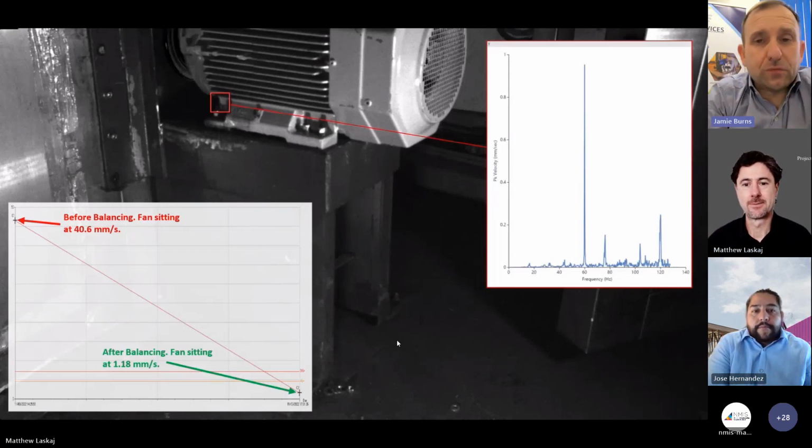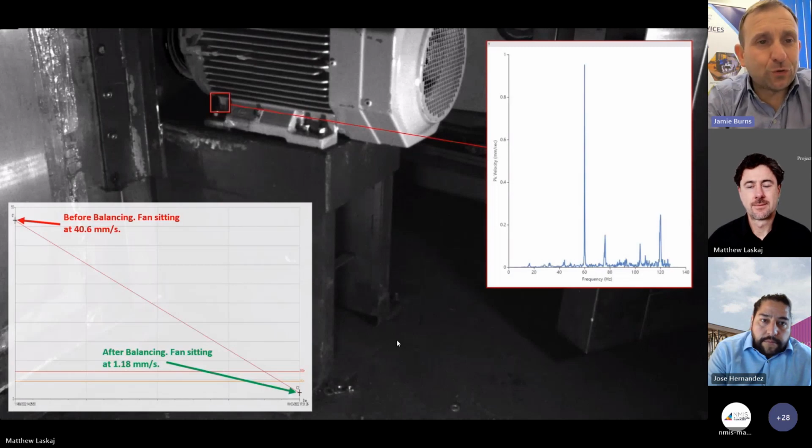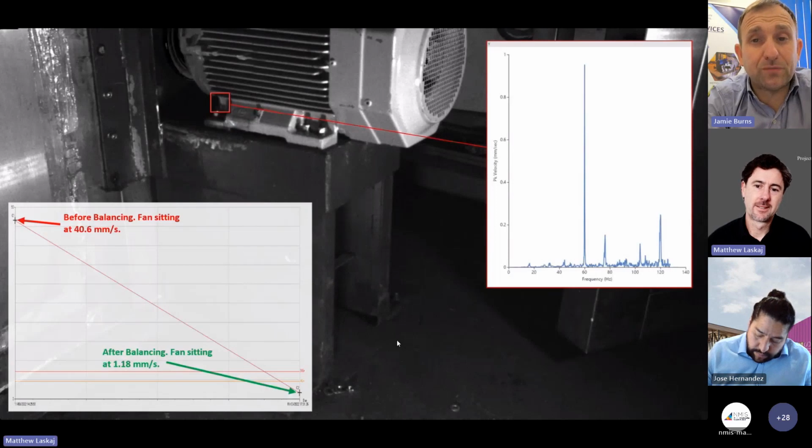Obviously, you get a lot of times where you're going round machines and they're vibrating excessively, but it's just down to things like the bolts, and not the right type of washers put in. Maybe the wrong torque has been applied to them to begin with, because these things have to be installed properly. A lot of them are moving at quite a high speed, so there's a lot of torsional and rotational forces being applied. You need to make sure you put them in right.